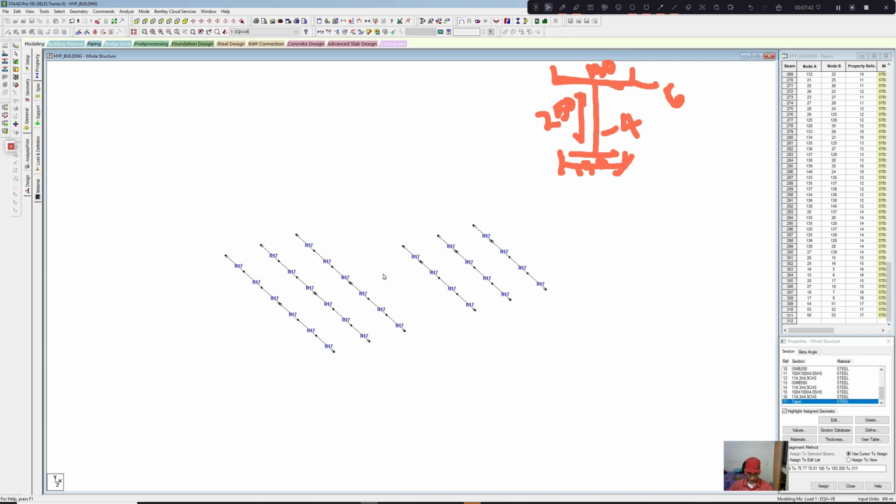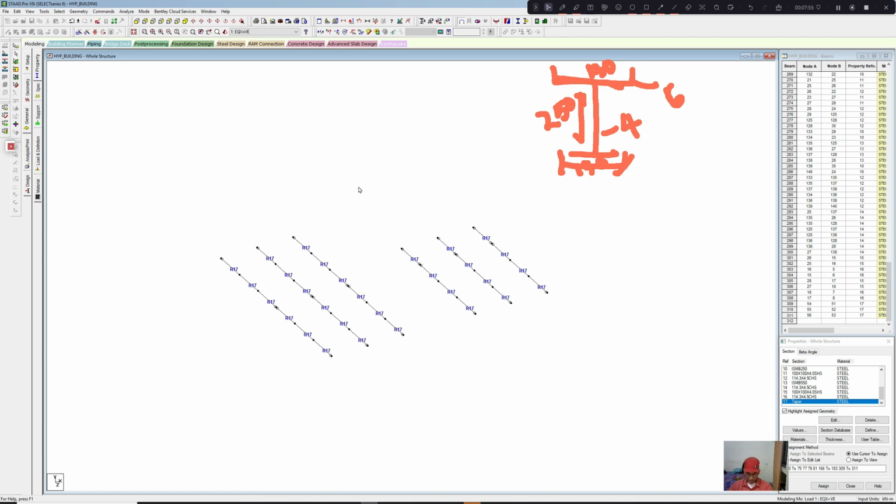That requires a P-delta analysis, which is not in the scope of this tutorial. Usually, in most cases, you don't need to remove this, and many times STAAD Pro actually issues wrong warnings. So let us see what has happened to this joist.